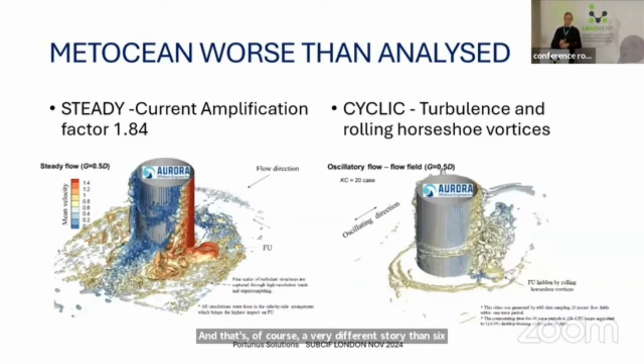It's because we have these cyclic shifts that are generating these horseshoe vortices around the foundations, circling around the foundation. This is the big thing that has basically given the big problem with the cables in the offshore wind industry, and has given us the problem with the CPS systems, the washing machine effect, that have killed a lot of CPS systems.